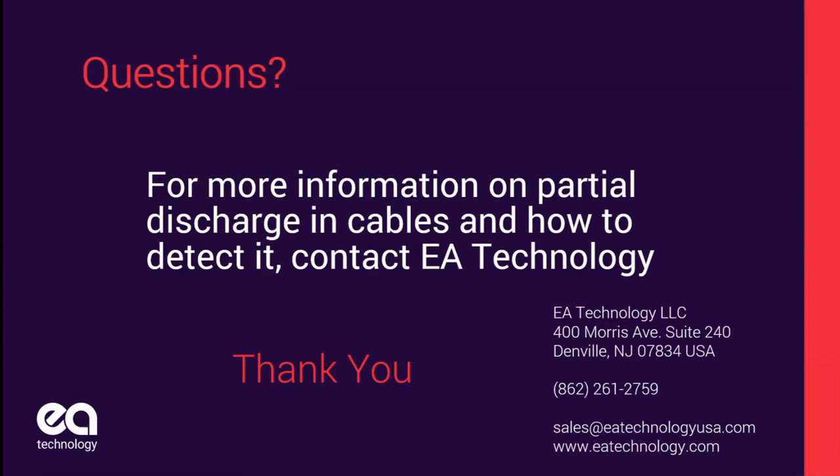All right. Does the RFCT require single point ground of shield? What if grounded at both ends? It doesn't require it. If you have cable shielded at both ends, you will get some division of the PD current, and it's going to be less sensitive. But then you can also test it at both ends. If you have a single point cable with an SVL on the far end, you're going to get all the current going through the ground shield, and you only need to test it at one point. You can't test the other end.